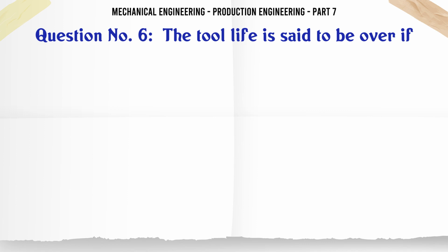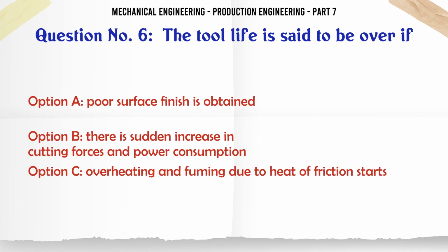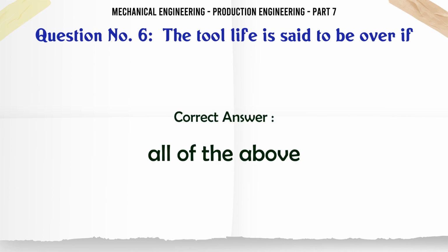The tool life is said to be over if A) poor surface finish is obtained, B) there is sudden increase in cutting forces and power consumption, C) overheating and fuming due to heat of friction starts, D) all of the above. The correct answer is all of the above.